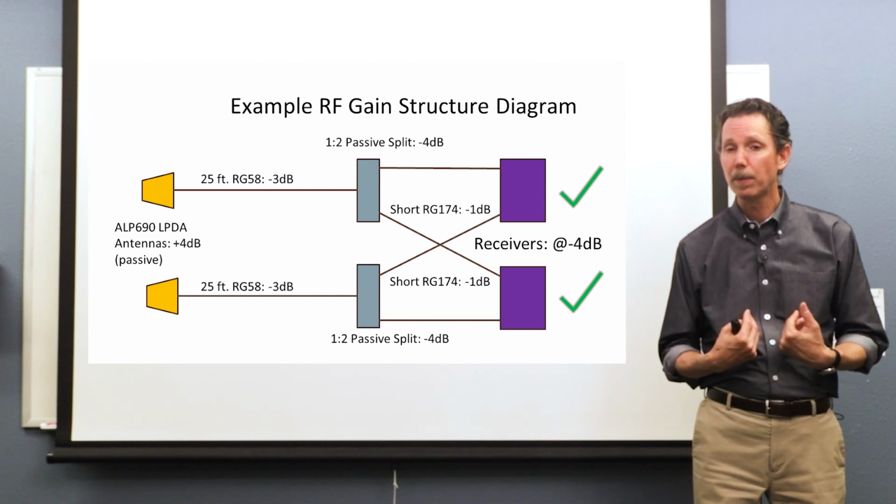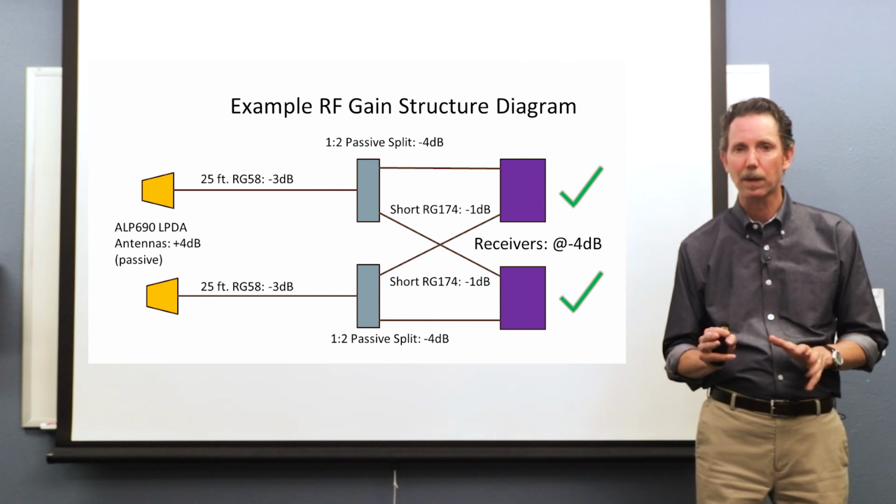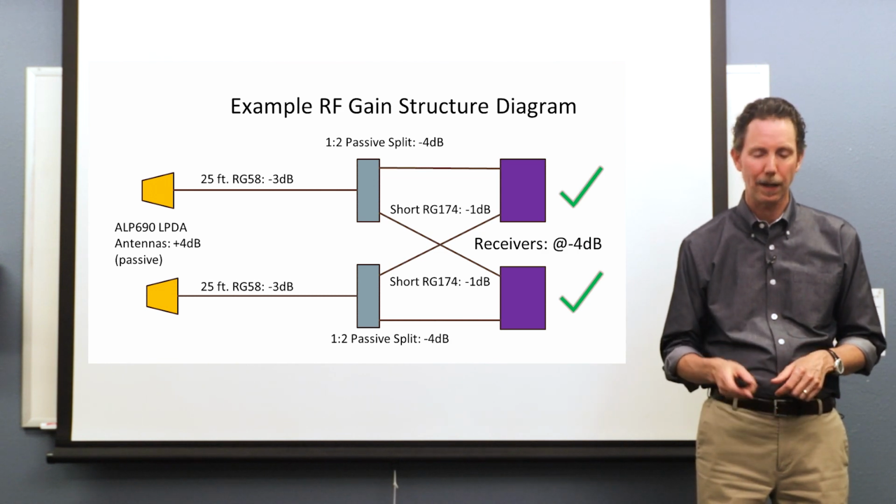Now, in my opinion, a little bit of loss with a passive system like this is preferable to too much gain, okay? So, in my opinion, this system is good to go. This will be a very high performance wireless system, assuming that it's good quality components and that the antennas are set up in a good place.